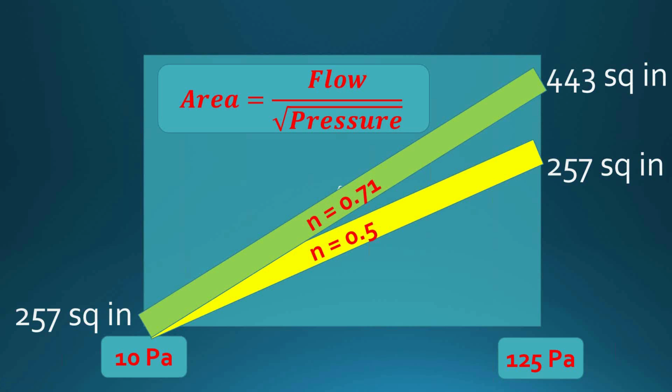The question here is hold time prediction based on 85% of design concentration. The current version of NFPA, and probably for some time, four or five years or so, counts all concentrations as being the same for descending interface, but not for continuous mixing. So its model is of a sharp interface, which means we've got air above, agent below, and we go from 0% agent to, let's say, 10% agent, and there's no interface in between where it goes through a transition. And I'll show you some pictures of that later. So they're actually all the same.